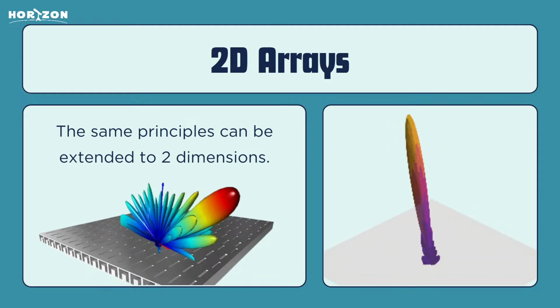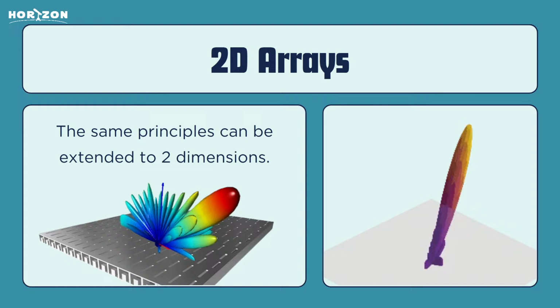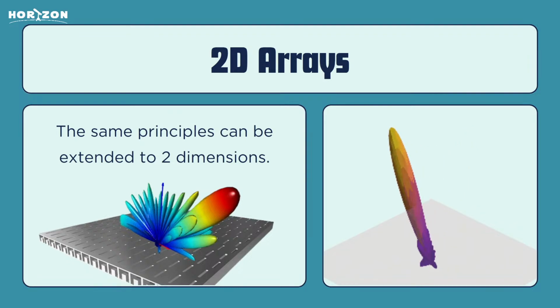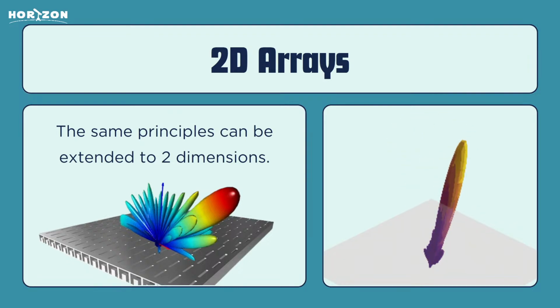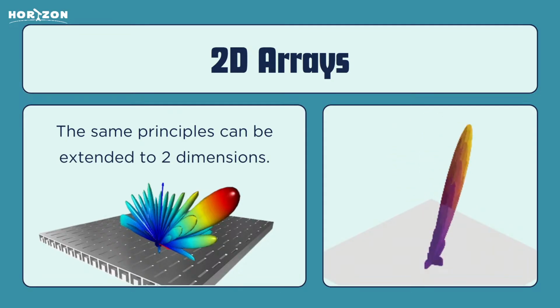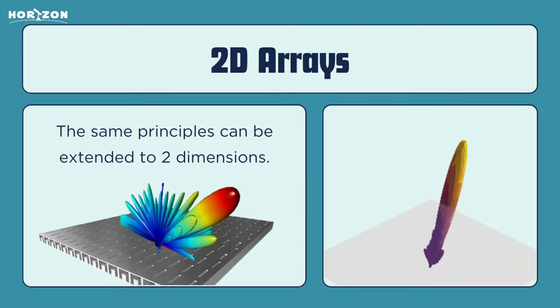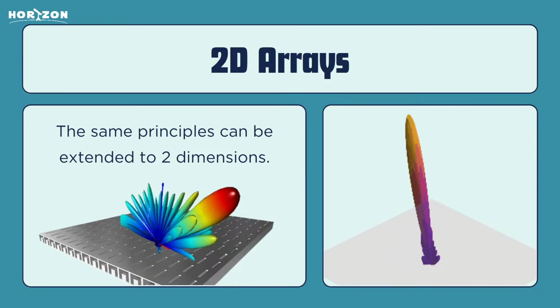One more extension to all of this is that instead of just playing around with the phases from the electronically controlled phase delays, we can also add an attenuator there whose attenuation we know, and that in a sense helps us reduce the side lobes even further and increase our directivity even more. So we can create more spindly shaped radiation patterns, which can be useful to look into a more narrow part of the sky.